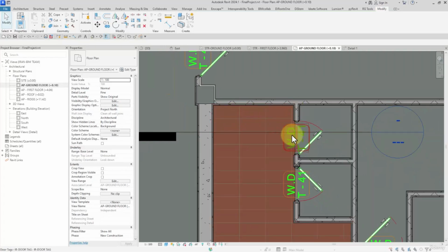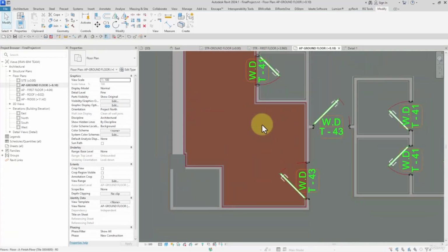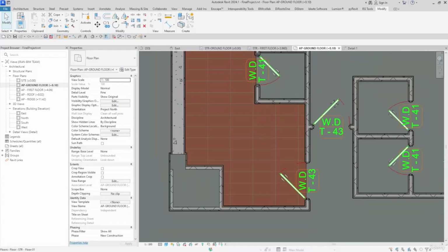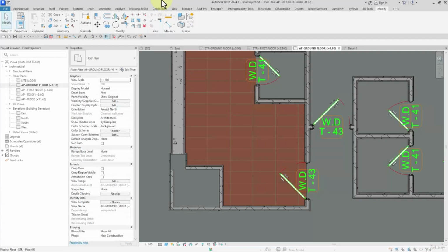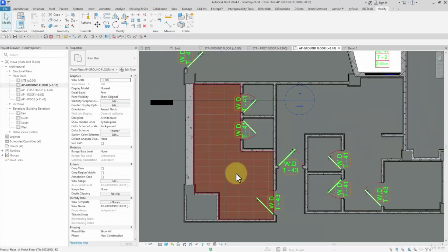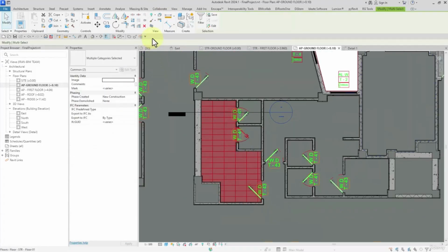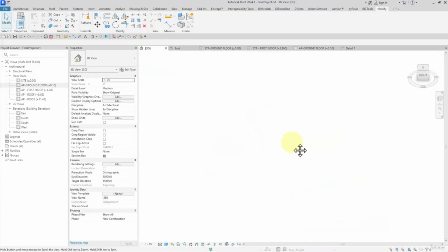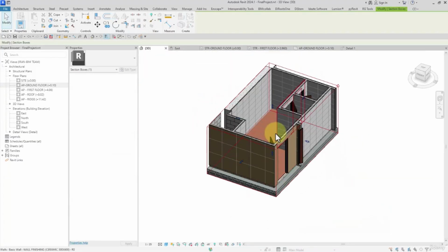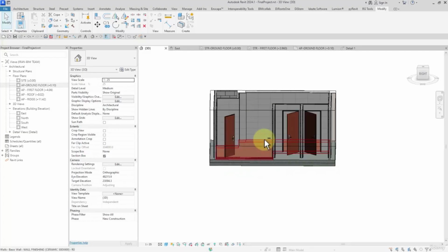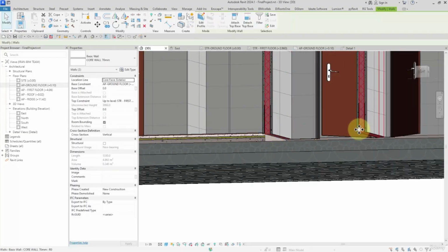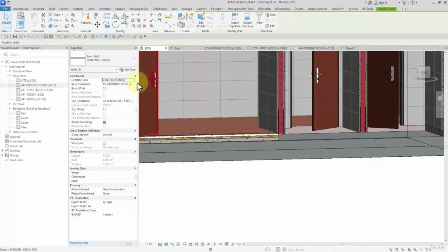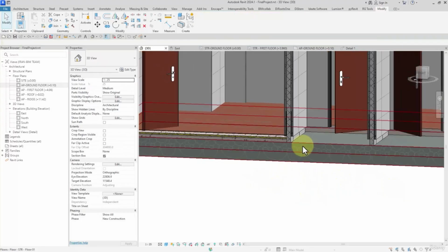by this way. So I have added the tiles from the left side. Check this out. This is the result. Like this way. Both are the same. And right now, if I check it out in a section box, check this. Here it is. For example, these parts are left. So we select them. Ground floor, structure.